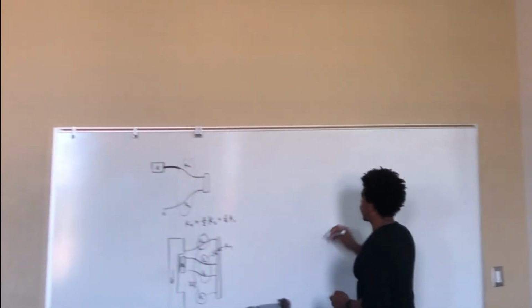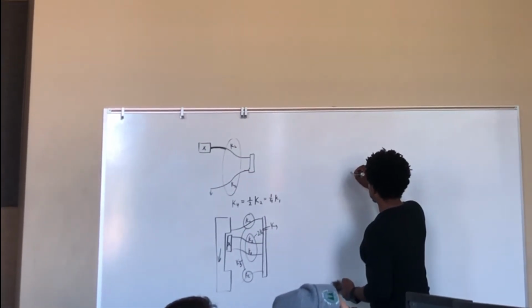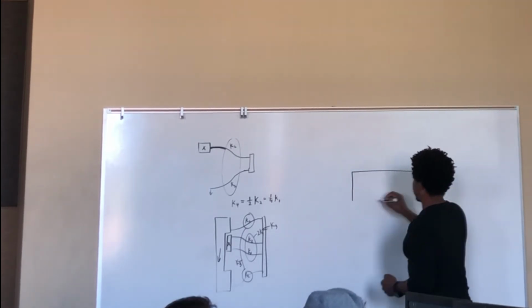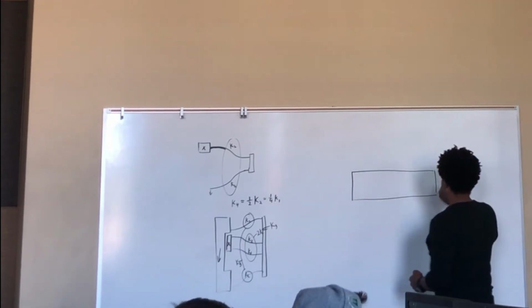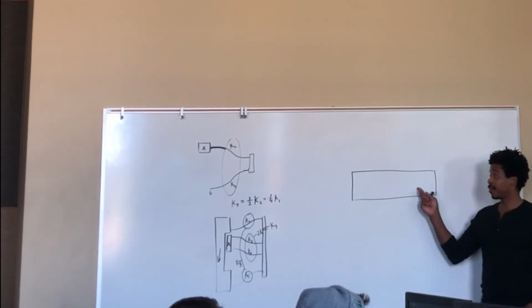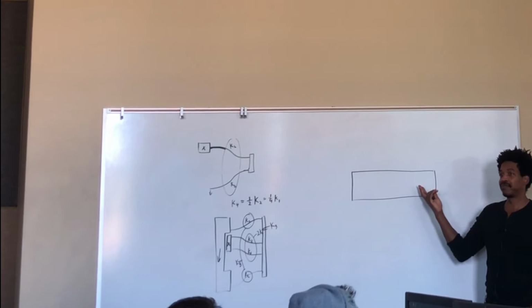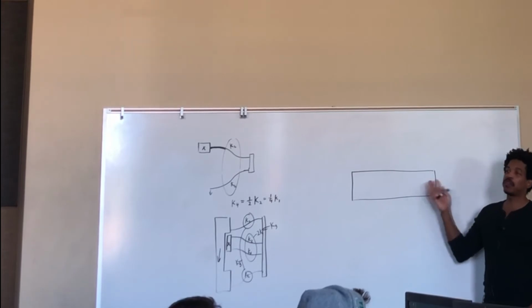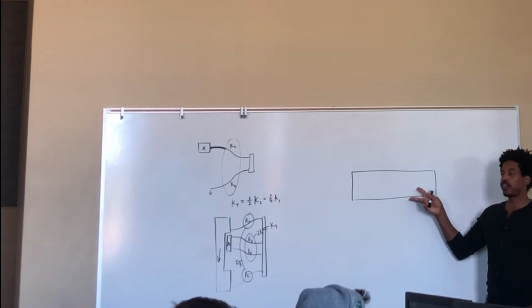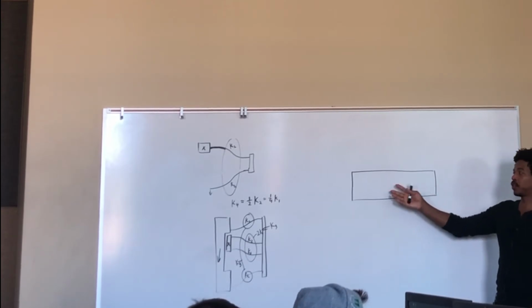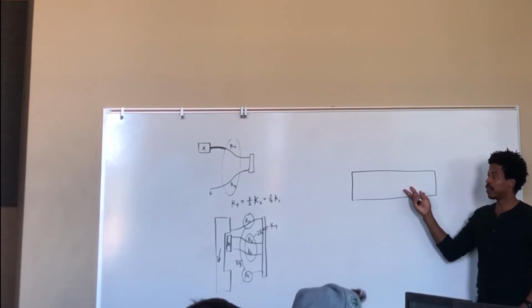when you do computer-aided engineering or design in COMSOL, because you're dealing with FEA, typically you just start off with the geometry, and in this case, it's just a simple rectangle. Now, what does this represent, like right now? In COMSOL, it doesn't represent anything, it's just a shape. It doesn't know the physics yet. Okay? So when you start to model things in COMSOL, you have to define what that shape is. Now this is just a cross section. It's in 2D. I could do it in 3D as well, but it's just a cross section, right?